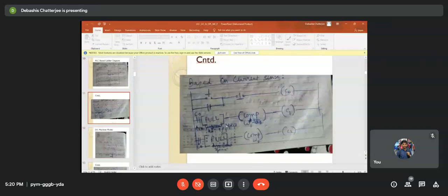So pull speed, that means the speed input is in the register from where we are fetching that data, and then comparing with omega 1, the desirable speed, omega 1. When it is equal, C1 will be 1. Now again, C0 is here, and I am pulling the speed, and I am comparing with omega 2. Then C2 will be 1. Then in the next rung, I will compare with omega 3, and so on.